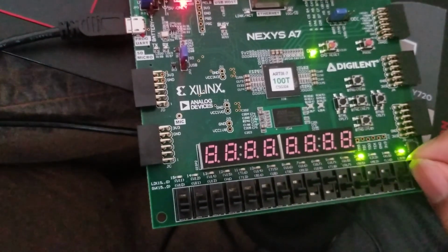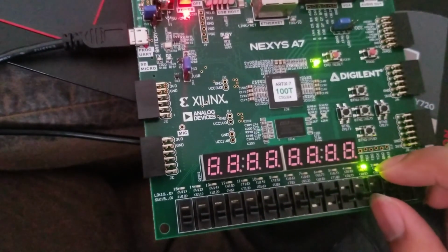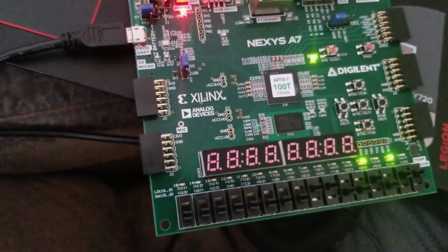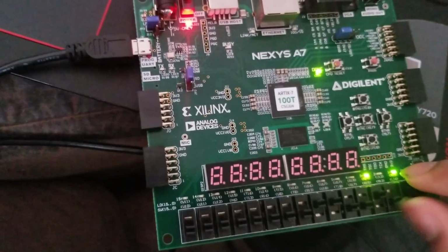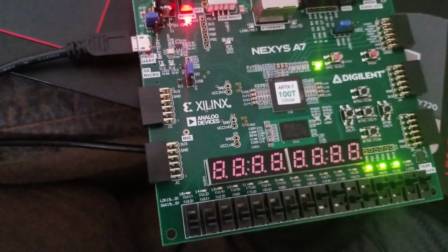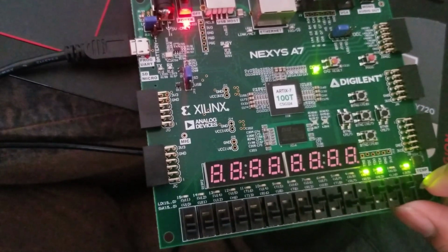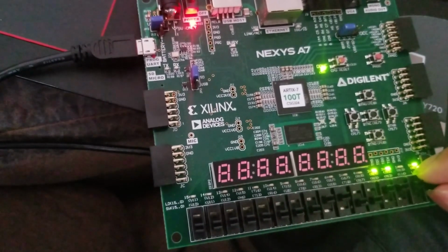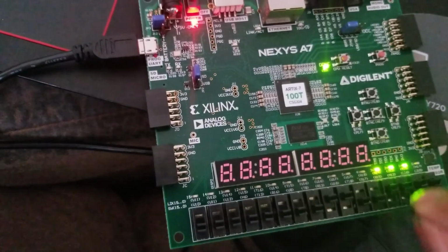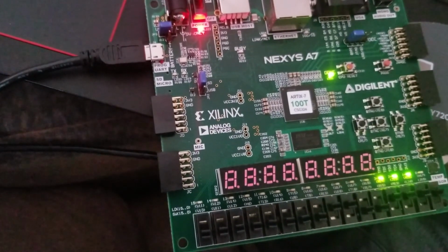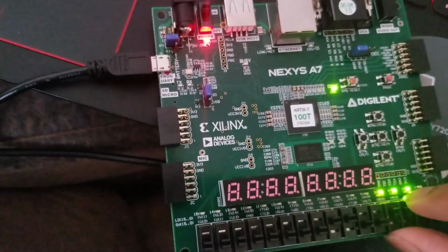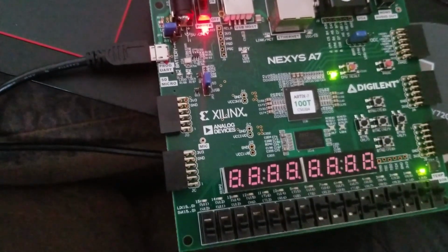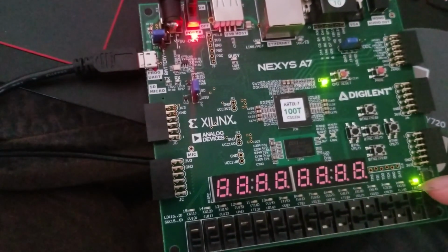So if we were to turn A up to 3, and turn on B0 up to 1, we would see that in subtraction we would get 2, which makes sense. If we were to turn A up to 6, we would then get 5 as our output, and if we were to turn this up to 7, we would get 6 as our output. And then if we go into our AND mode by putting M1 up to 1, we would see that the only ones that are ANDed are 1.